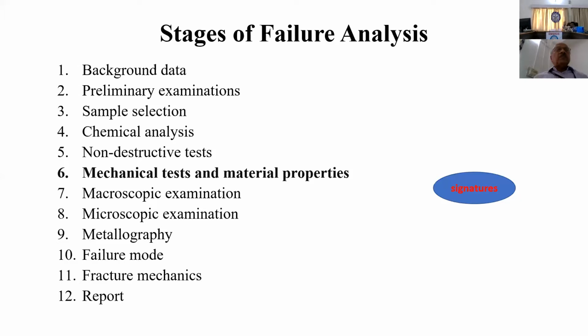That is normally followed by macroscopic examination, microscopic studies, metallography studies, failure mode analysis, fracture mechanics analysis, and finally, of course, the report and recommendations.